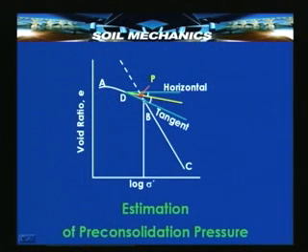There is one other important concept, that is, we have been talking about decompression and recompression, and when we recompress up to some point of time, the stress is within the value of the stress to which the soil had been compressed earlier, and that stress to which it had been compressed earlier is known as the pre-consolidation pressure, and it is very often important to know this pre-consolidation pressure. There is a method for computing this, which we shall see in the next lecture.